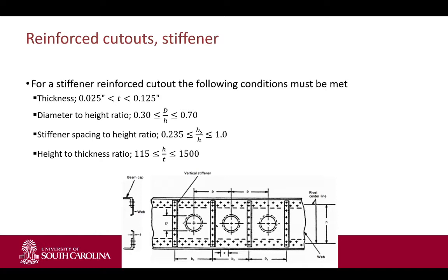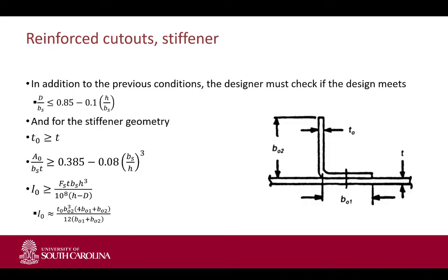And the next important step is when you go into reinforcements. So we basically add riveted sections to it, a donut, or additional material around the hole. So the equations change a bit. If you use an L stiffener or a different type of stiffener, everything changes. And what you basically do is you take into account the area of the L stiffeners in your analysis. And it's a first order analysis, so it gives you a rough estimate, but in most cases it's sufficient for your preliminary design of your aircraft.